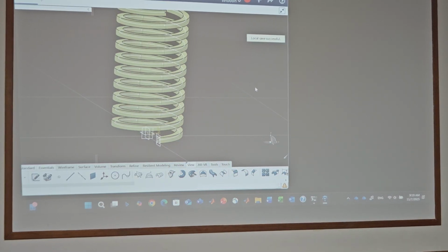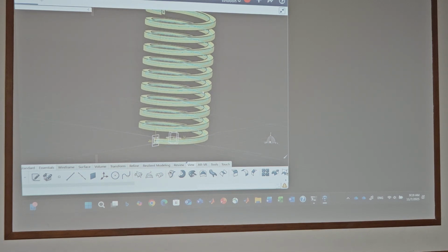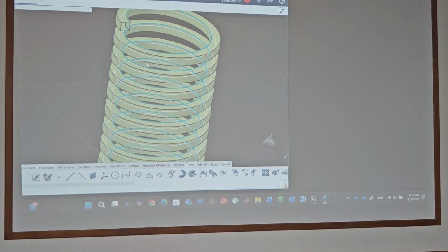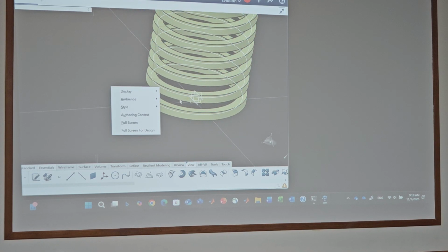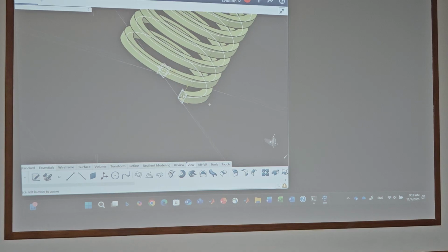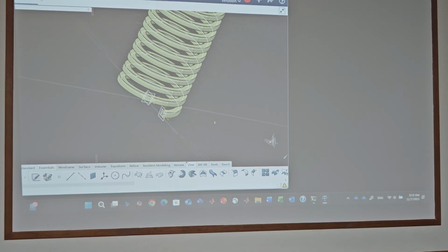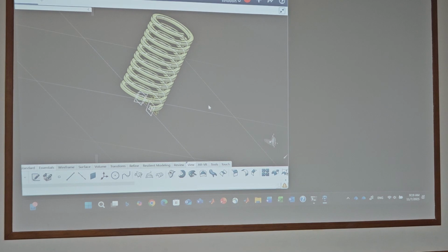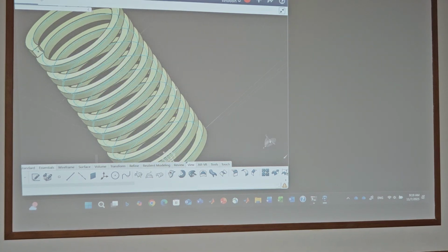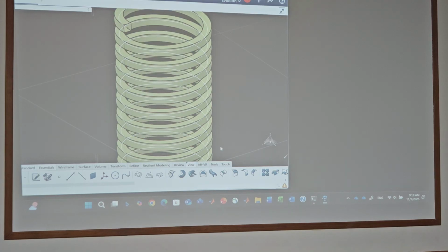Okay, so this is a surface anyway. If you want to convert it to solid, you have to close this one. Close this and close this, right? Okay, plane actually, and join them together and use close surface to make a solid, right? You can do this one. Let's see.